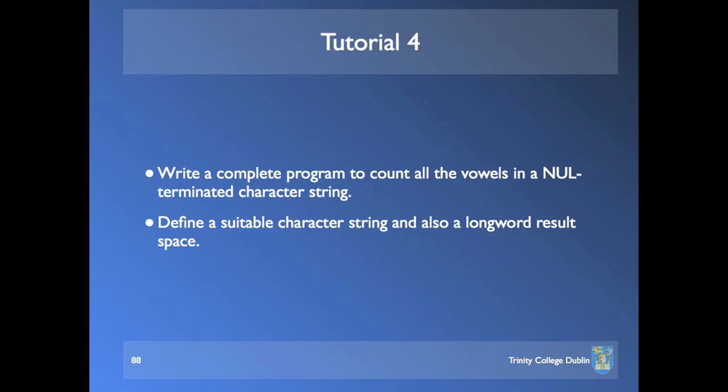Is there a big difference between adding words and long words? Is there a speed difference? Well, if the operands that you're adding are all in the processor, there's no speed difference. No. But if you're adding, say, an immediate value that's part of the instruction, well, that immediate value has to be fetched. And if it's a word or a byte, it'll take 1 bus cycle, and if it's a long word, it'll take 2. So it'll be a bit longer if it's long. Okay? But I will show you how to manually calculate that, approximately anyway, so you can work out for yourself what are the best instructions.